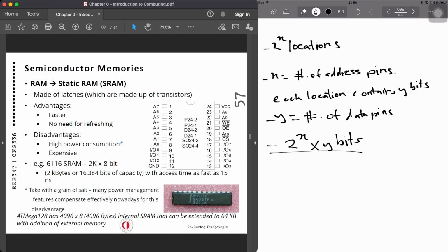Now the problem with the use of the flip-flop for a storage cell is that each cell requires at least 6 transistors for implementing a latch, and the cell holds only 1 bit of data with 6 transistors. Then they developed a 4 transistor version, but still too many.